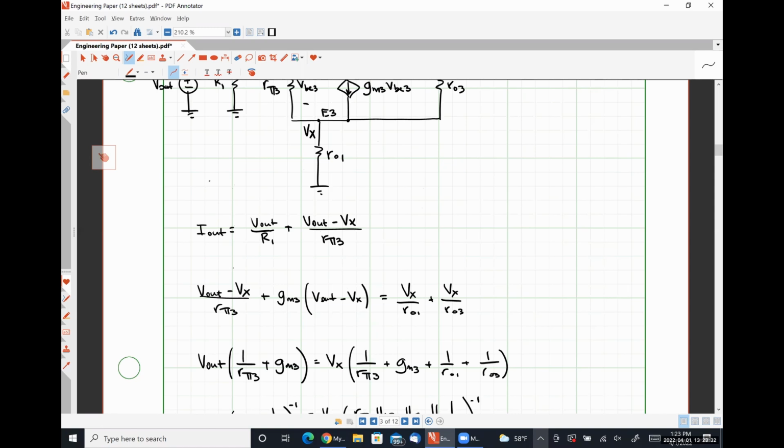For a source follower, in the homework you proved that it should be, so that would be a common drain or common collector amplifier, it should actually be negative GM. So really the only thing that you're not sure about would be something that would be common gate or base related. Everything else, you have a pretty solid idea that it's going to be either positive GM1 or negative GM1.